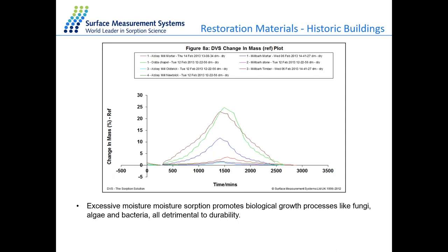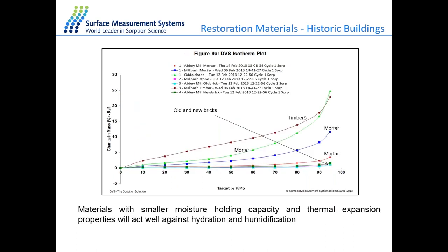However, what I wanted to show you here is, for example, the difference between older bricks, so older material, and newer material. The older material usually has a higher uptake of water in the higher end of our curve, compared to newer material, which tends to absorb less water but also be more reversible. If we plot the kinetic data, you can see here that from older to newer, our isotherm plot squishes towards a lower level of uptake compared to the older material, which usually tends to have more water in it and maintain more water inside the structure.